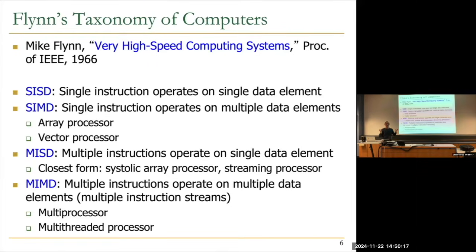That's a lot of overhead. If you look at the energy spent on an SISD processor, most of it is really spent on the overhead, not the computation itself. This is another way of thinking about it. I'm not even talking about memory over here. Forget about memory. This is just the computation that you try to do and what is required to enable that computation. It means to fetch the instruction, decode the instruction, etc.